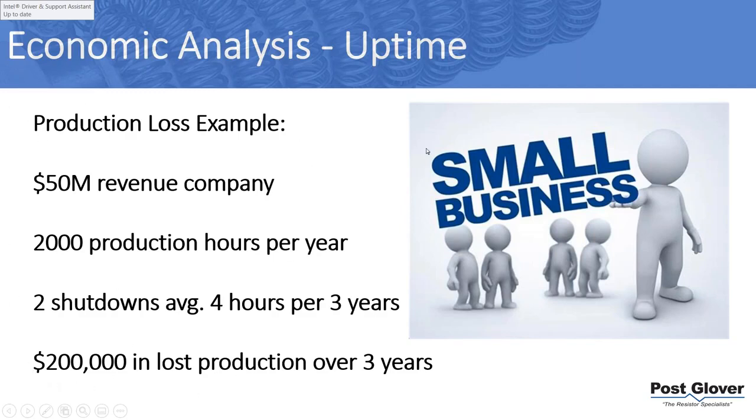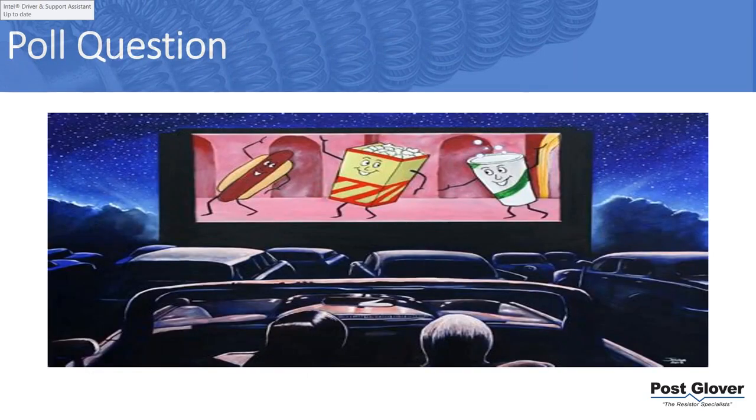Once again, will high resistance ground help with 100% of this? No, but it will help with a lot of it. And I can't quantify it, but I've tried to a little bit in the data center world. The point is that loss due to ground faults, lost time due to ground faults is definitely an issue, and high resistance ground will help with that.